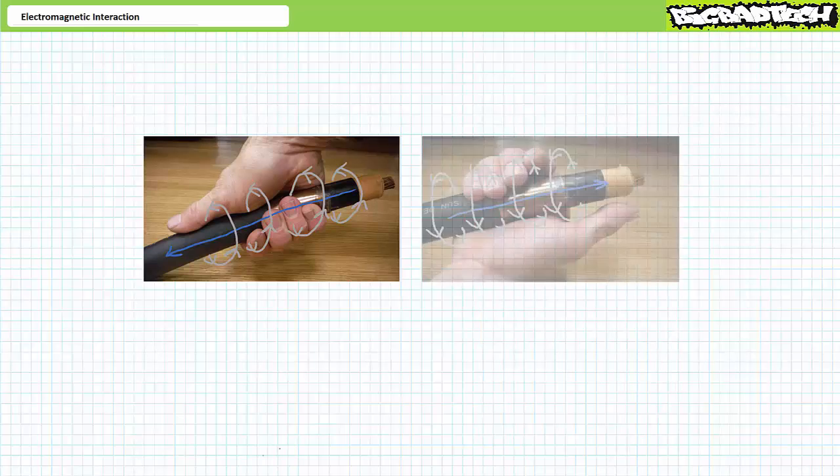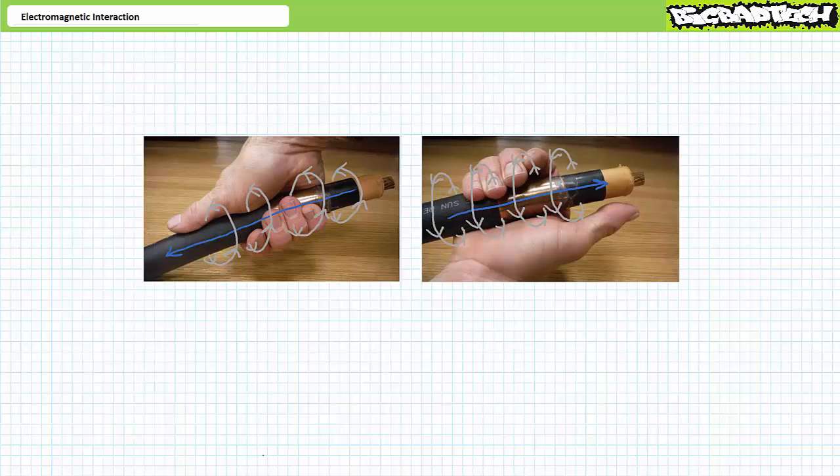It is an observable fact that as conventional current moves through space, it creates a magnetic field around it. The polarity of the resultant magnetic field can be predicted by holding the right hand in a loosely held hitchhiker pose with the outstretched thumb pointed in the direction of conventional current flow. The curling fingers indicate the polarity of the revolving magnetic field north to south. You'll note that current flow in one direction creates a given magnetic polarity orientation, whereas current flow in the opposite direction creates a magnetic field of opposite orientation.